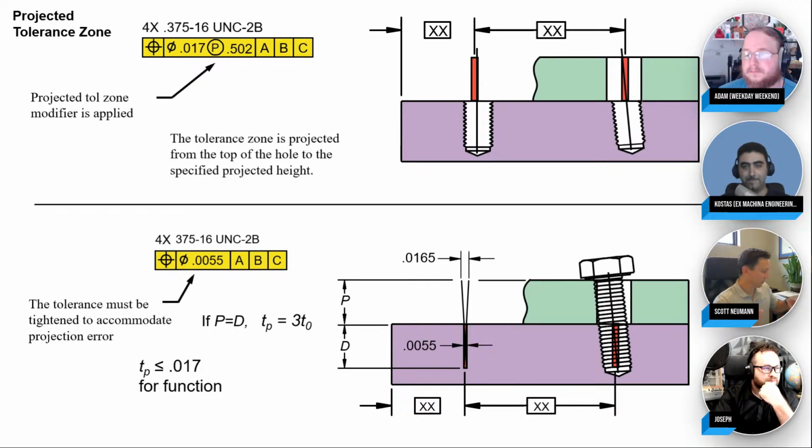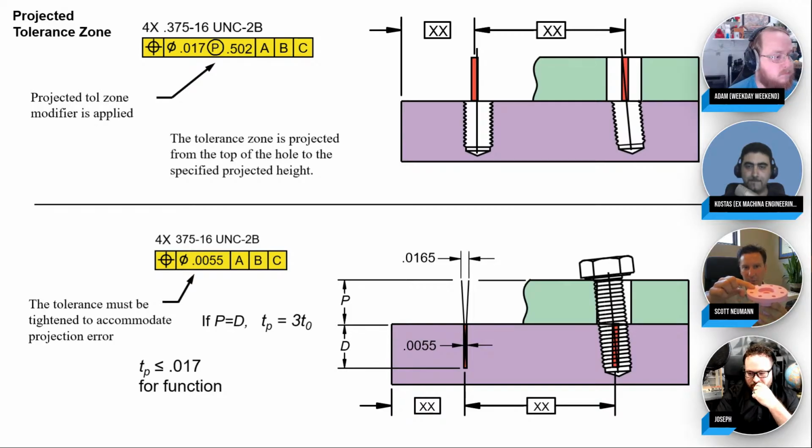Inspection loves it too, because let's say you have a part that has some blind tapped holes in it like this one. So let's just say these are blind tapped holes going into the part. How do we check it at the height of the part and then sticking out? Oh, just use a thread gauge. So stick a thread gauge in there. I got a couple thread gauges. There's a thread gauge. I got a few of them here. There's another thread gauge. Another thread gauge right here.